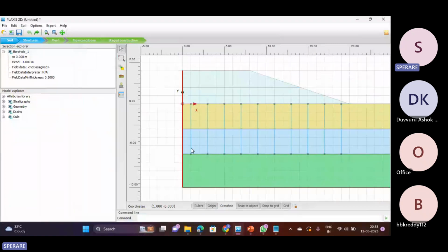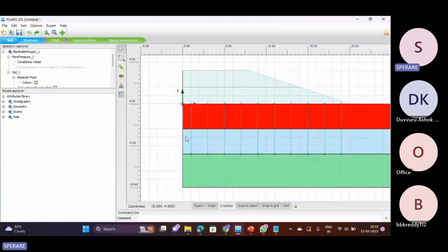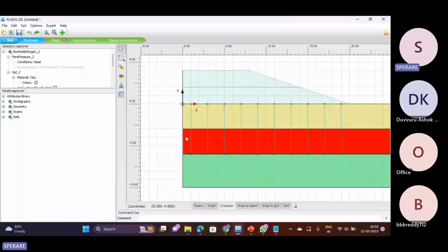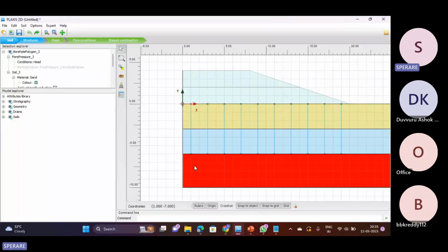My drains are coming over this region and this region, and these two regions I'm calling with undrained A material properties. If this particular material property is also undrained A, having a huge amount of water content that needs to be calculated, I would consider this better. But in my particular problem, the structural element is not touching that particular layer, so treating it as drained is also fine for me.